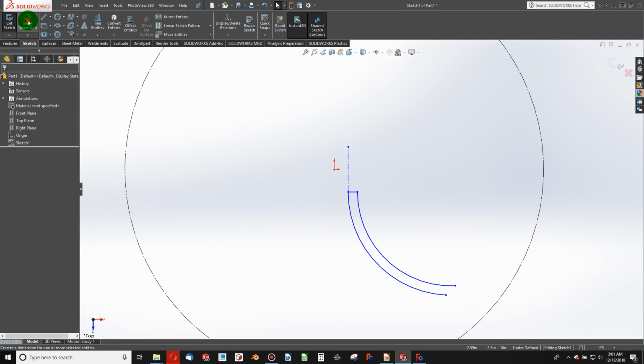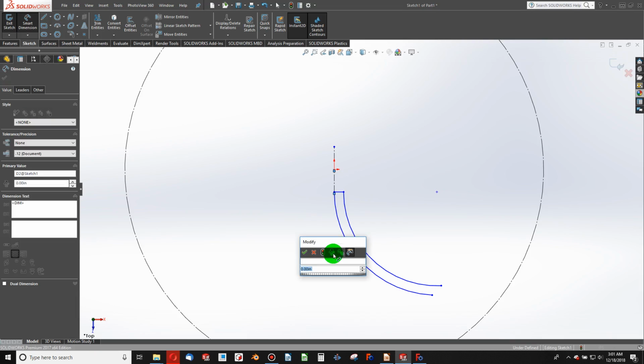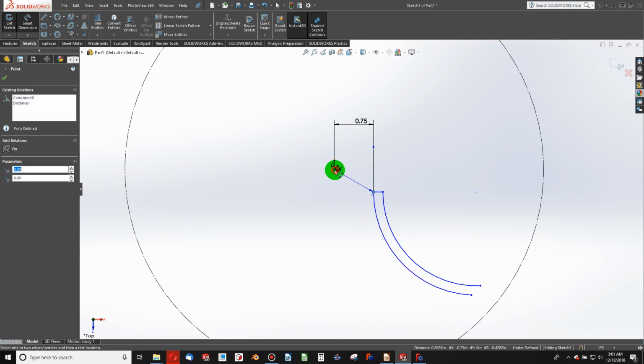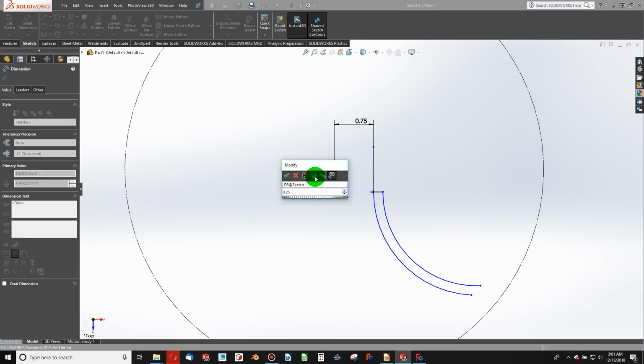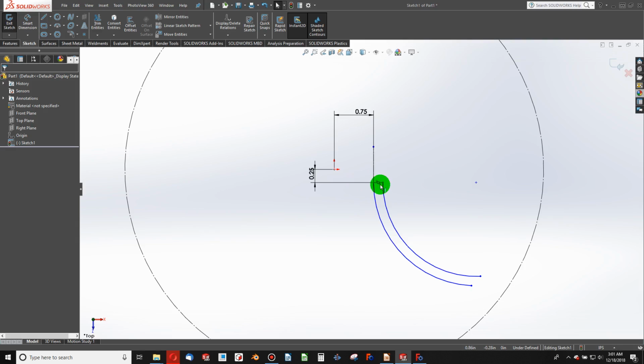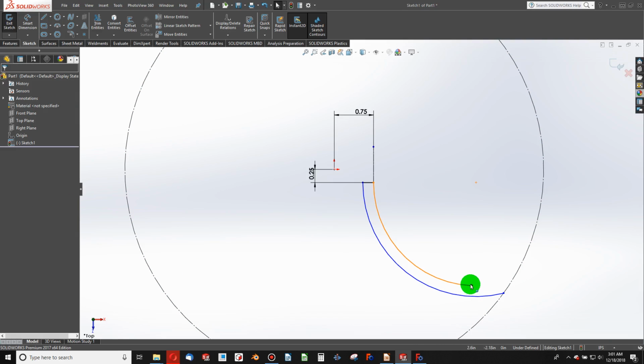Okay, with some of this sketching, I'll go 3/4, I think it was. Whoops. 0.75, and then I believe I was a 1/4 inch here. When I revolve in FreeCAD, I find that it comes out best without any errors or anything when the blades do not touch. So I add this little extra 1/4 inch and this 3/4 inch over here to try to loft ideally for FreeCAD and not have them touch.